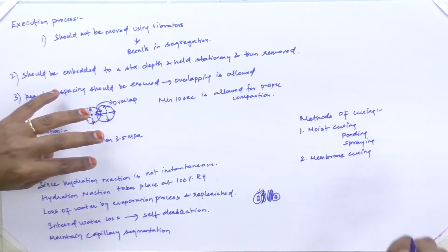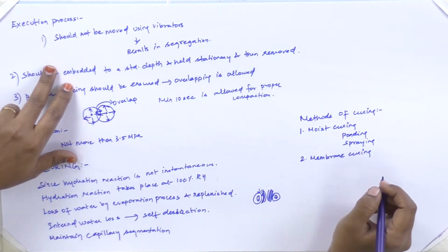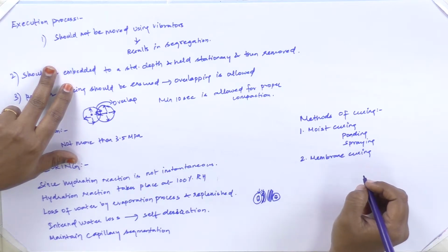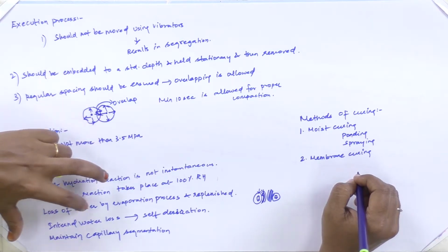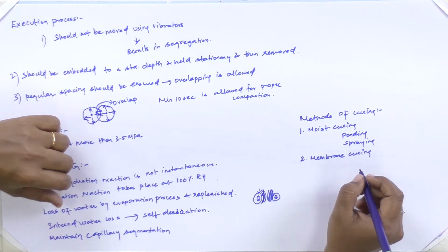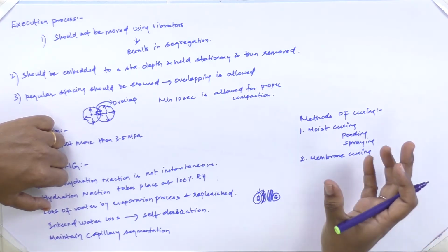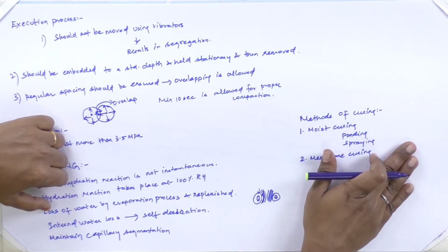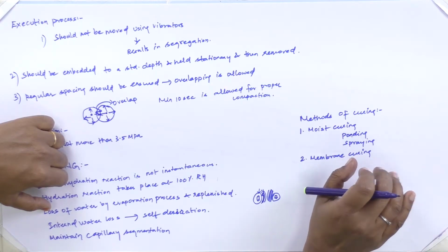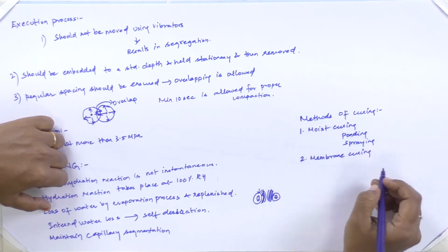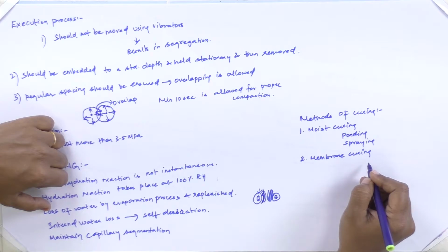curing. In membrane curing, we will see that the water is not lost due to any evaporation process. That is, the amount of water which went inside the concreting process will remain as it is when we go in for this membrane curing.